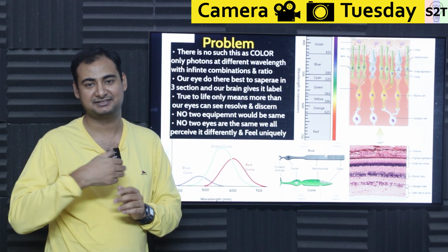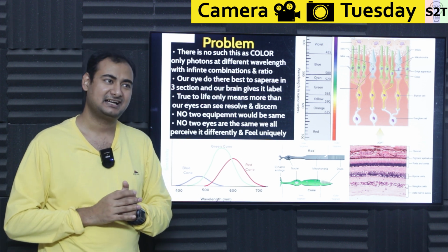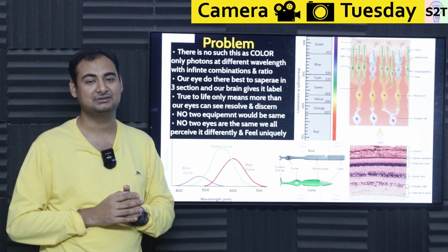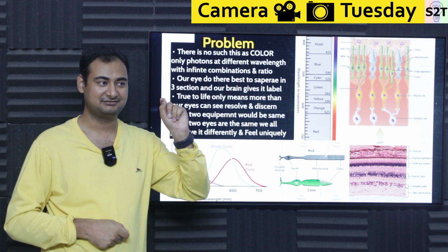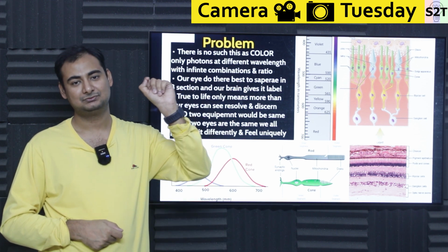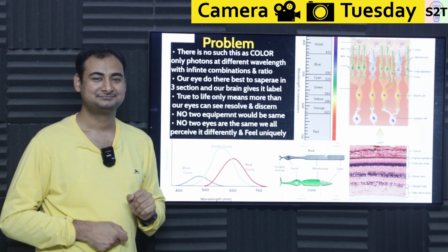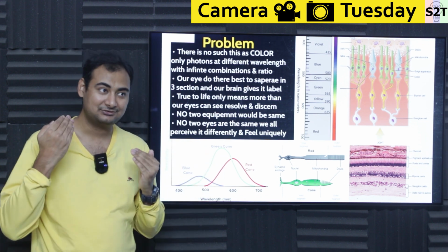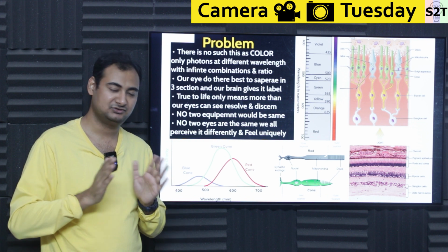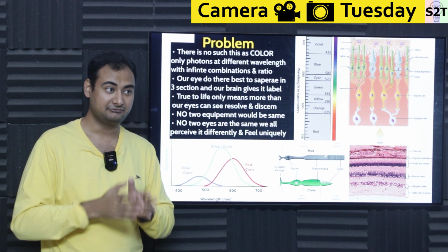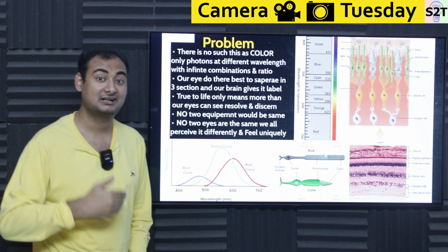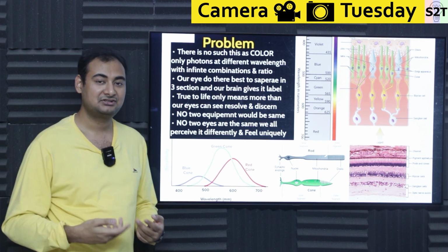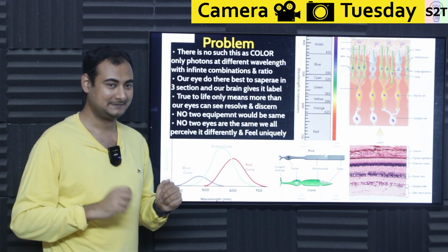Some figured, hey, just put a blank. But then the color calculation becomes far more complex. So somebody said, hey, our eyes are sensitive to green, put green there. So we have green, blue, red, green again because of this. And that's how we tried it. Be mindful, do not think about this like it's a random thing. We tried every other option. It just looked ugly to us. Why? Because it was not matching how our eyes were perceiving it. So it always felt like the camera is broken.